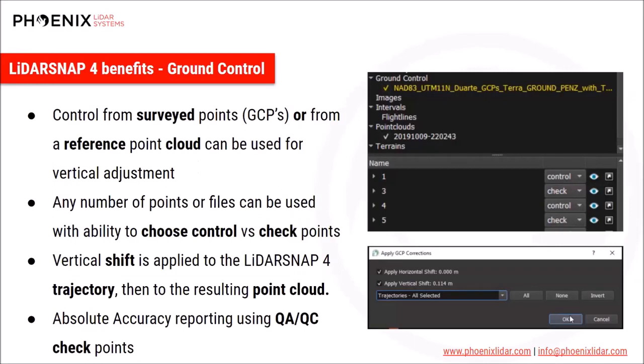And also ground control. We're able to bring in ground control from a multitude of files. These ground control files can be in different projection systems, so long as the user knows. So say you get control from 2 different survey companies. One uses ellipsoidal height, one uses orthometric, one is living in a UTM zone, one is living in a local state plane zone. These can be utilized at the exact same time in the exact same project because Spatial Explorer 6 has a project datum and projection.